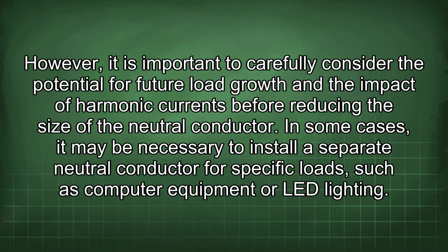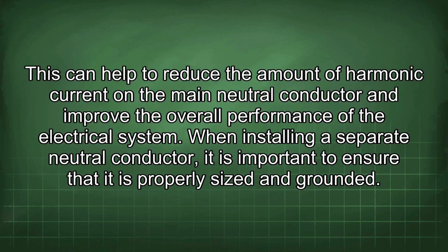However, it is important to carefully consider the potential for future load growth and the impact of harmonic currents before reducing the size of the neutral conductor. In some cases, it may be necessary to install a separate neutral conductor for specific loads such as computer equipment or LED lighting. This can help to reduce the amount of harmonic current on the main neutral conductor and improve the overall performance of the electrical system.